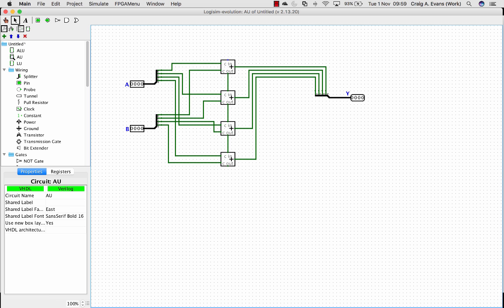You just need to be able to handle this carry in and that carry out. So we just need a single pin. So let's call that C in for carry in, and then the output is a carry out. Let's call that C8. So that's a 4-bit ripple adder.